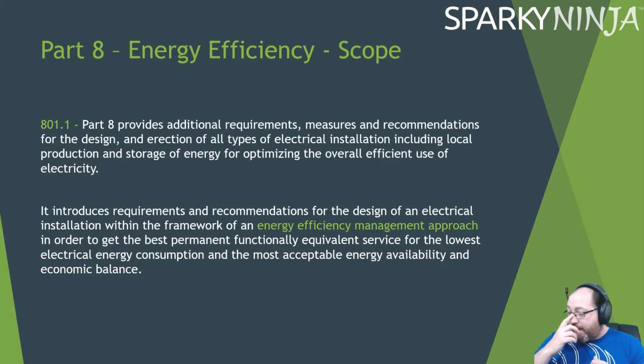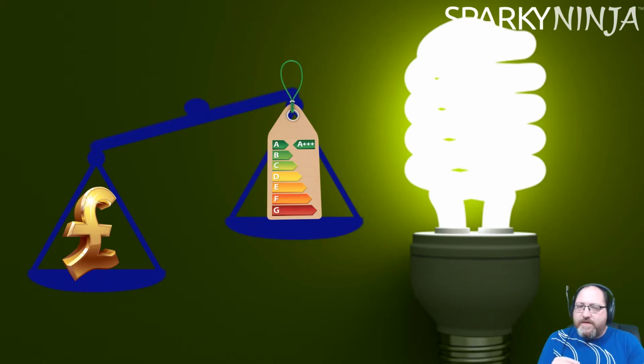The problem with that is industrial, commercial. We have certain considerations: LED lighting, and considerations with using renewable technologies, but one of the main concerns is we also consider cost. An example of the changes under consideration now is things like cable sizes. When we do our cable exercises, we normally say, right, let's try to calculate them to be as small a cable as possible to save money. So we make sure that we size it for thermal effect, so it's heating under load, it's not going to create a fire, and we save money that way.